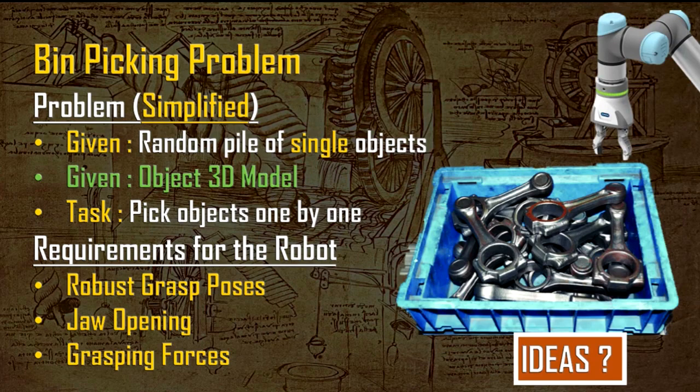A bit on that, but I have this one doubt. Every time we pick and drop, the heap will start reducing. Then it will go deeper, and the joints have to turn deeper to pick the objects. So the distance of the objects from the camera will start varying, right? It will increase. So do we need a depth camera over here, or depth knowledge? How exactly are we going to determine that?